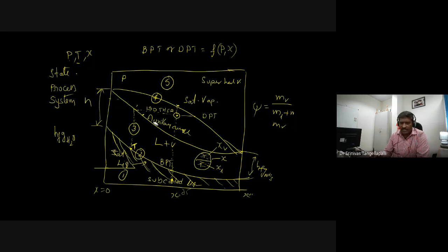Okay, this I am calling the horizontal line, which I am calling an isotherm. It touches the saturated vapor curve at one particular point, and if you draw a vertical line, it cuts the x value. You show this as XL, the vapor related one is called XV, and the mixture is related to X. This horizontal line is called an isotherm because it is a line of the same temperature, related to the liquid and the vapor curve.